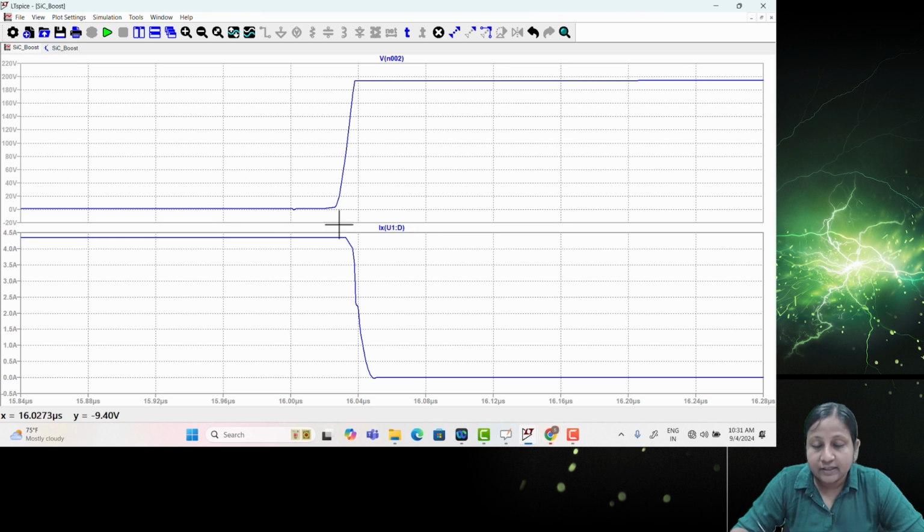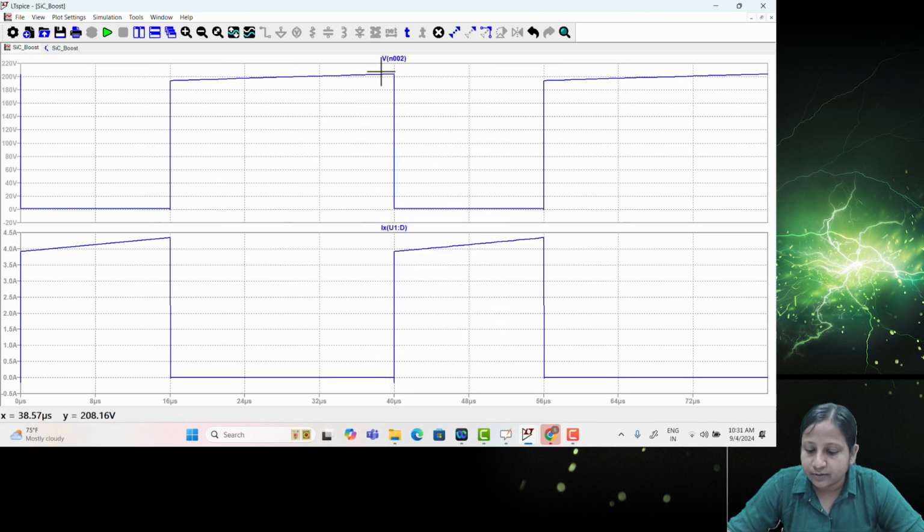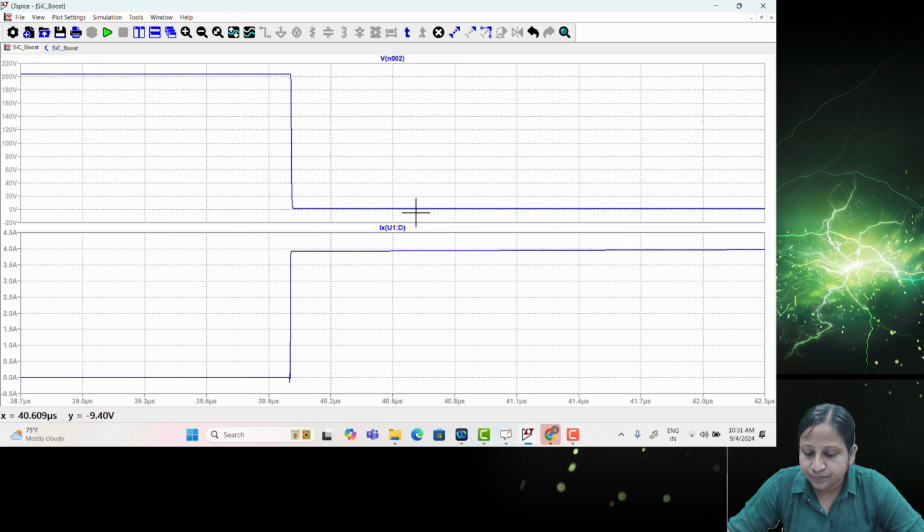It is a clear kind of waveform. It doesn't have any oscillation. This clear waveform is not what we can see in the practical circuit. In a practical circuit, the oscillations are visible, similar to the simulation results you have just seen with parasitic elements. Now see the turn on time. The turn on of this will also be very clear. See, this is the turn on part.